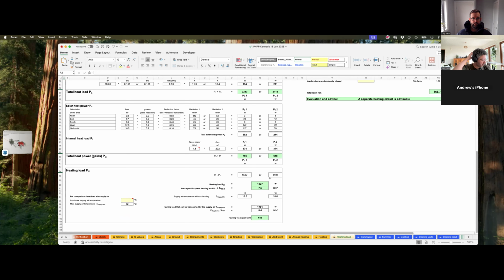And look, because they're cheap, air conditioners tend to work better if you oversize them a bit. You'd probably put a 5 kilowatt upstairs and downstairs. Unless you're going to put split systems in bedrooms, in which case you would just run 2.5s everywhere. I think that's the smallest. I don't think we're doing that. I'd rather the 2x5s.